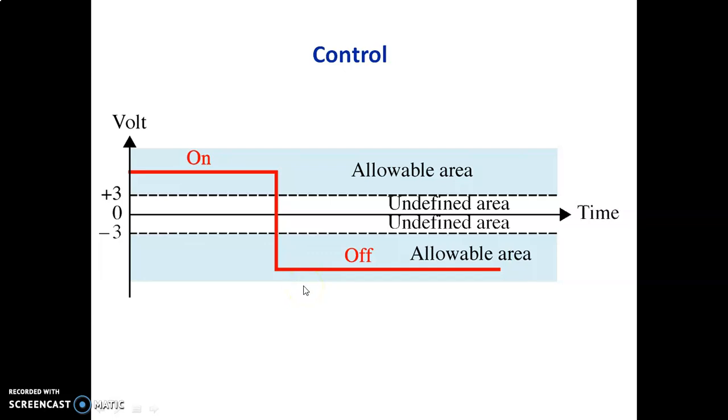Only 4 wires out of the 25 available in an EIA-DTE-DCE interface are used for data functions, and the remaining 21 are reserved for functions like control, timing, grounding, and testing. The function is considered on if it transmits a voltage of at least +3, and off if it transmits a voltage of less than -3 volts. The electrical specification defines that signals other than data must be sent using off as less than -3 volts and on as greater than +3 volts.